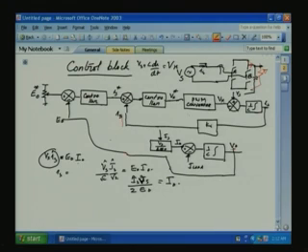Okay. And all our control here is through PWM. So, we will assume the PWM frequency is so high that during the control action we can assume this IC, the sinusoidal part of this current with a small ripple, is not changing much. So, we are using a sinusoidal current reference and sinusoidal current feedback here.